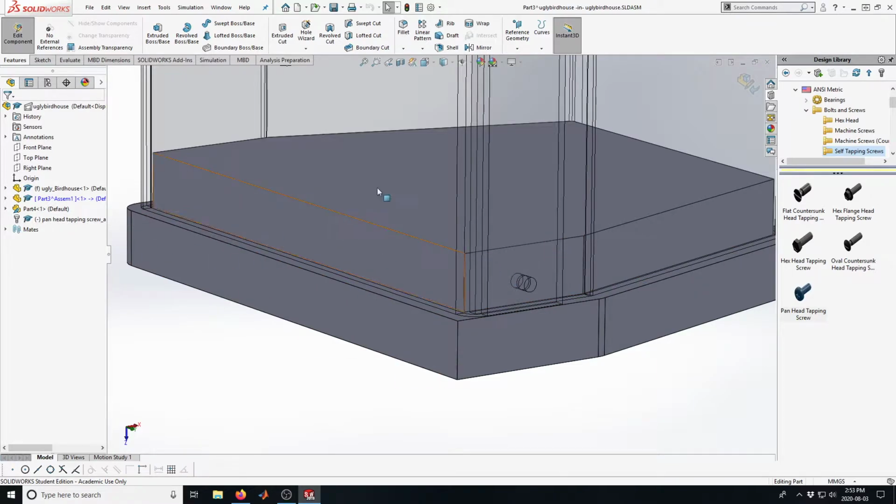Now you'll see when I click that, first of all, confusing, because this is one of the confusing SolidWorks things, it looks exactly the same as it just did before I clicked that. Only difference is that my part 3 is now blue in the feature tree, or the assembly tree, and up in the right hand corner I've got that symbol up here.